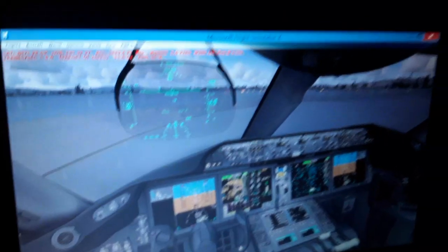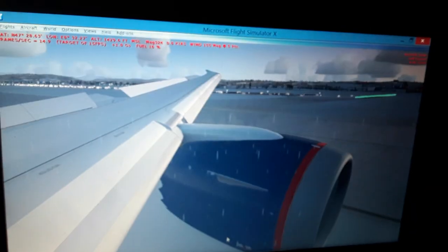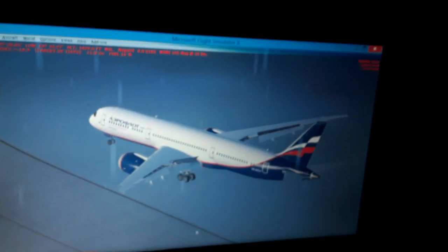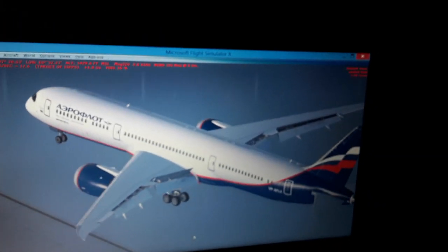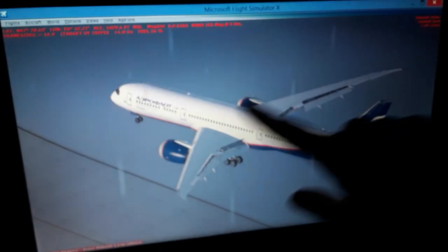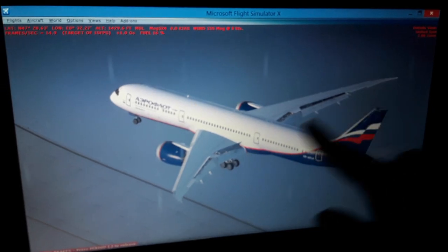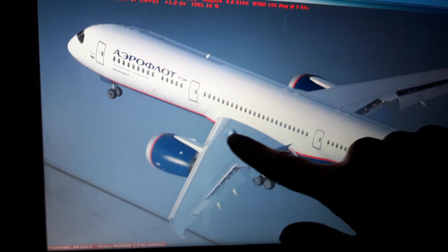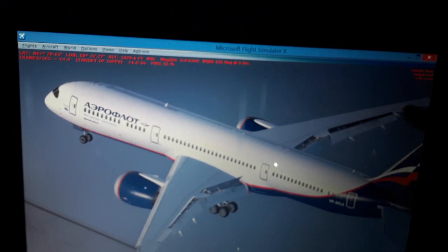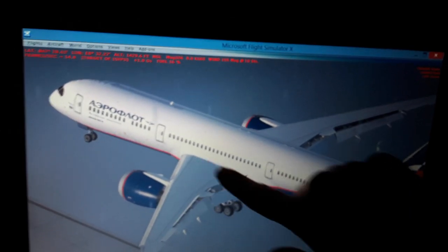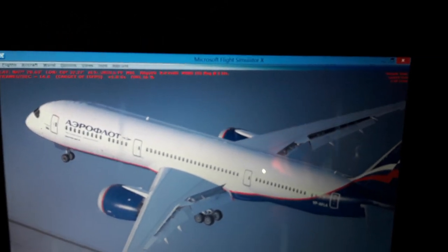So you can see here, I will talk to you about aeronautical and aerospace engineering, how to use aeronautical and aerospace engineering principles for the air transport pilot license. We need to know these are the wings of the aircraft that hold the weight of the aircraft as we fly. You can see we have the mean aerodynamic chord position. The MAC is about 33% of the chord of the wings, pretty much here. It's where the maximum aerodynamic lift occurs in the wings, where the stall also will begin for a given angle of attack.